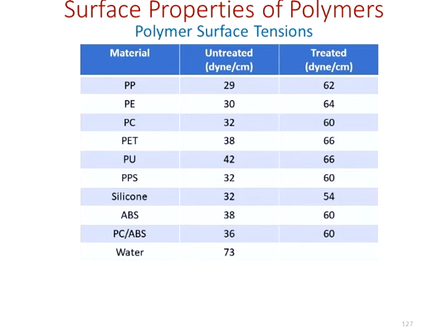So you notice here you can take these same polymers that are very hydrophobic. So it's 32. When you get down to the 30s, they're pretty hydrophobic. Okay, so you can take these hydrophobic polymers and make them more hydrophilic, more water-liking, once you treat them. That is one of the uniquenesses of working with the plastics. You can modify the surfaces. You can take the other mechanical properties, develop them, and then you can modify the surface for further interaction. And that's an important feature for them, and it improves their acceptability in the marketplace.